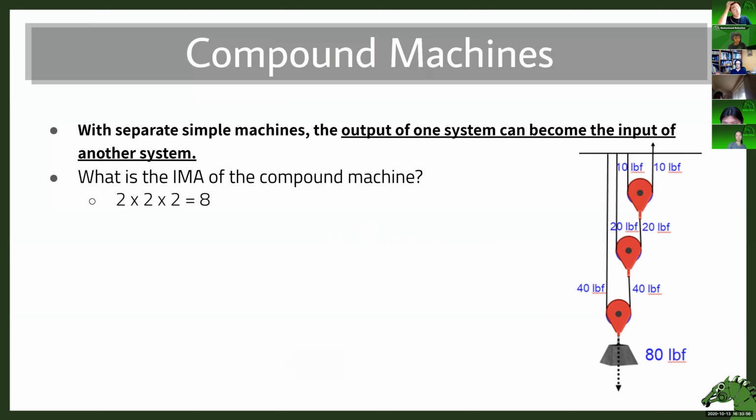All right, so that's how compound machines work, and that's how you get the net mechanical advantage or gear ratio of systems on a robot. A lot of the time you'll have things like gear reductions, then chain reductions, and then a lever arm that you have to figure out, or maybe a wheel and axle. So I'll show examples for that later.